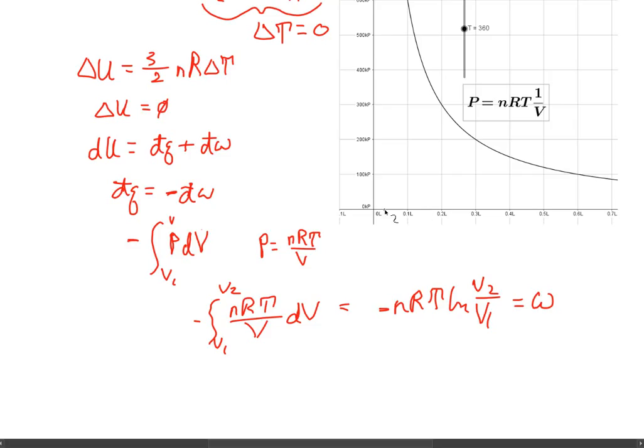So what we've shown is that in order to work with a pressure volume diagram and solve for work using an isotherm, all you really need to know is the first law of thermodynamics. The first law is given right here. And then in addition to the first law, you have to know the ideal gas law and a little bit of combination, and you come out with work. And we showed you how to find the area under the curve, which is just this piece right here. We showed you what it looked like. I hope you find this video helpful. Thank you for watching.